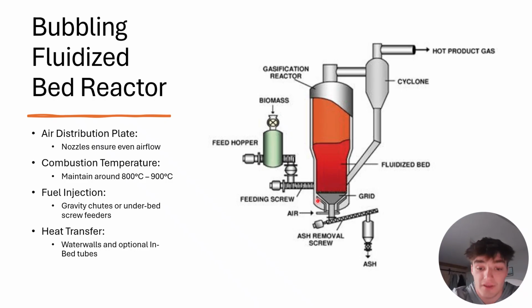Following the airflow at the bottom right here, the air is forced into the system and passes upward through the grid right here. This is where the bubbling occurs, and the air velocity is tuned precisely to lift the bed material, creating a turbulent liquid-like state. This motion is what allows for such high efficiency combustion, and the air is aggressively mixing with it in 3 dimensions. In terms of heat transfer, this system is unique since the fluidized bed consists of hot turning solids.